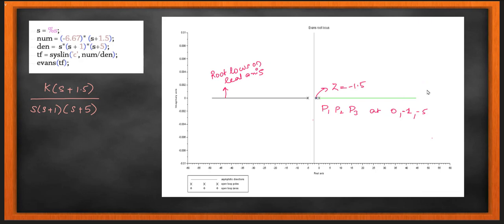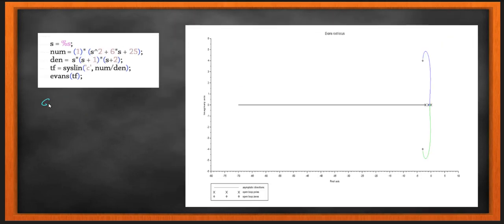Okay, and then that will be the centroid from the line. So now that is your asymptote, and the asymptote passes through the centroid. That point is the centroid, and there is no breakaway point. I'm just using this Scilab to show you the root locus of some of the examples, but I strongly suggest that you plot these, do these steps, compute it, and see.